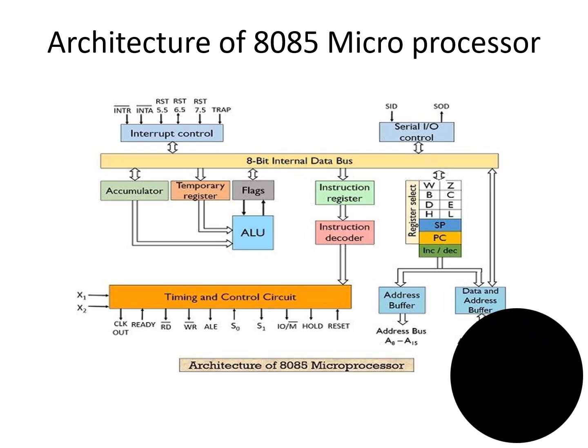This part will be able to compute this addition operation. And where will the result be stored? It is stored back to the temporary register through the accumulator, and that will be stored into the external memory location. And next up, we have the register array.